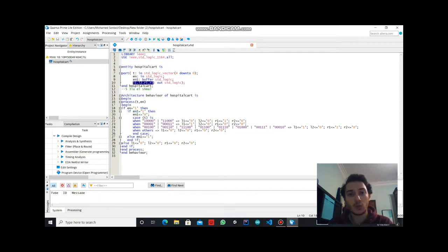And we have 4 output signals, 2 for each motor, right and left. For each motor, one signal is concerned with it spinning clockwise, and the other is concerned with it spinning counterclockwise, so basically making the wheel move forwards and backwards. Moving on, we move to our structure. It's a pretty easy structure. We start off with a process that triggers when either the input from our line tracker or the input from our proximity sensor changes.